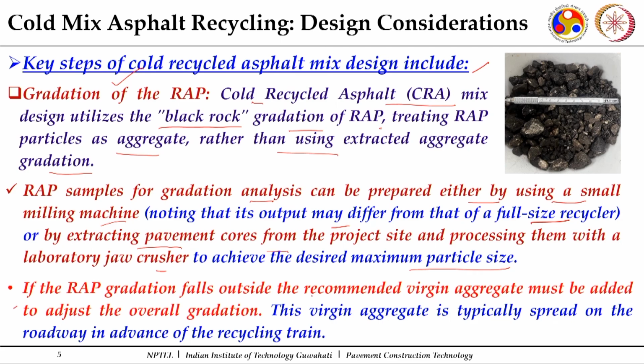If the RAP gradation falls outside the recommended range, virgin aggregates must be added to adjust the overall gradation. This is another important requirement.